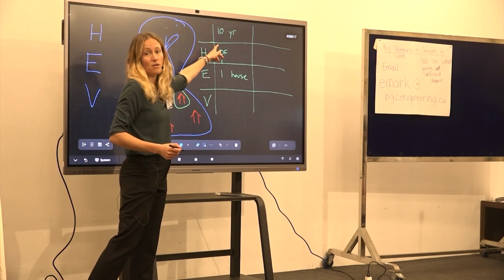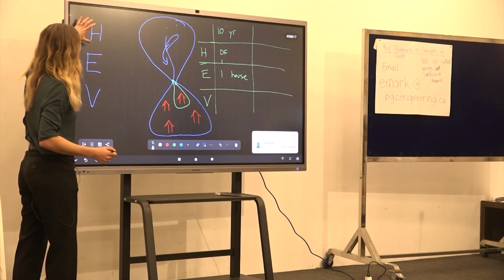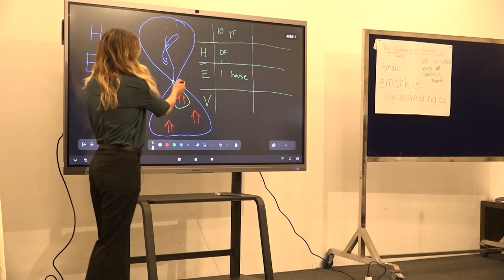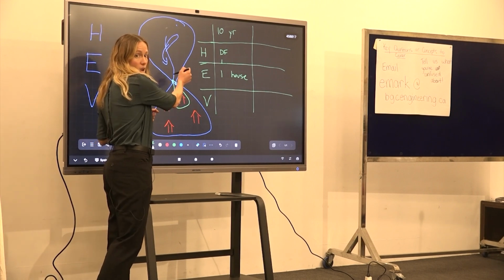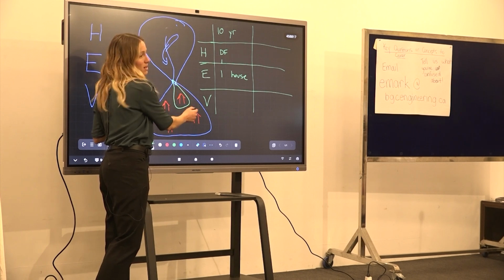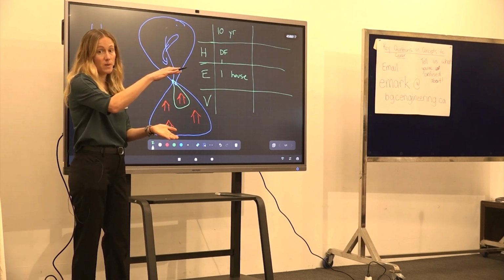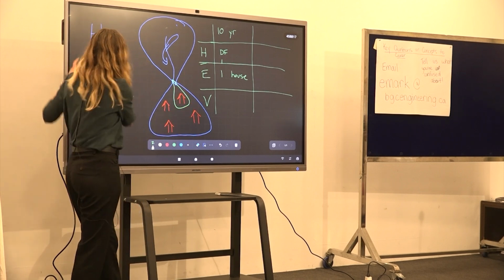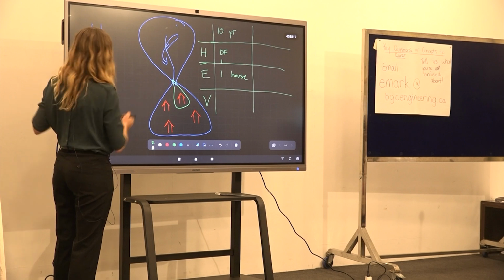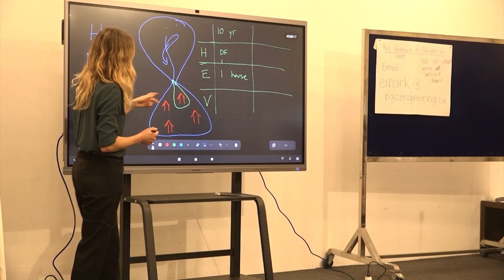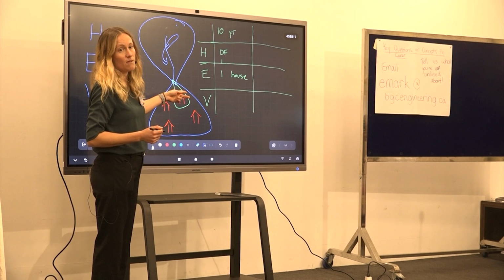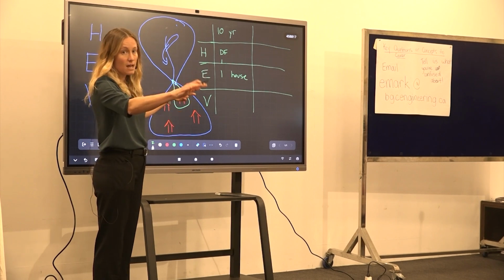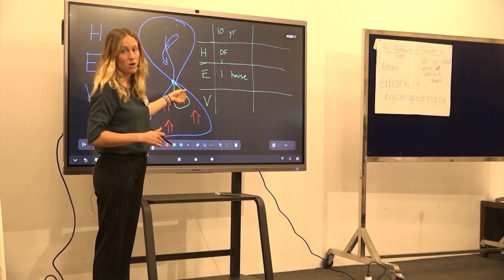And then the vulnerability is how vulnerable, how much damage there would be at that house in that 10-year event. And so you're gonna have your hazard probability, you're gonna do some runout model to figure out how far it's gonna go. The runout model will tell you maybe how deep it is and how fast the flow is moving at that house. So you know the house is affected, the one house is affected from your model, and then your vulnerability is in that 10-year event that's 2 meters deep and moving at 5 meters a second, how much damage will there be at your house?